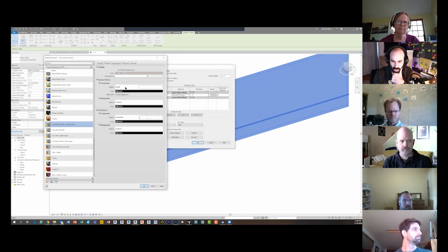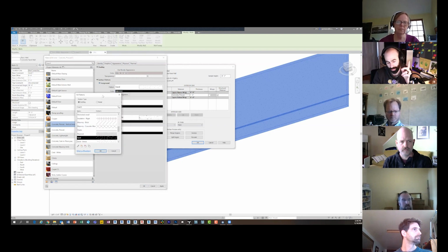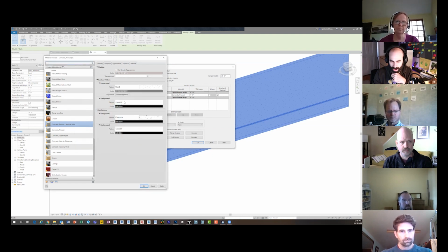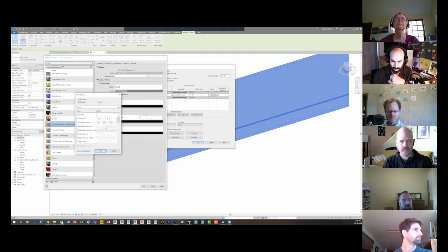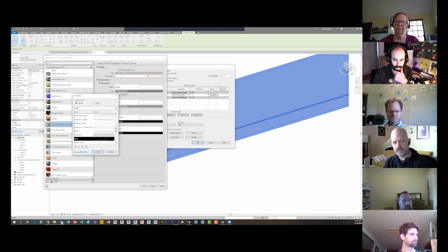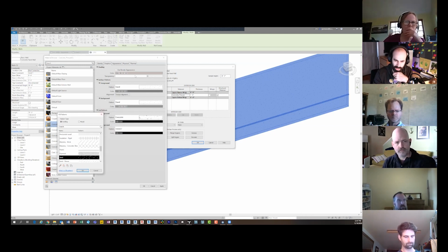And you can see I can just use a surface pattern. Instead of showing it as sand, I can go in here. Actually, pretty neat now with 2020 and 2021. I can leave sand if I want to because it doesn't look bad. I'm going to make it a little gray. And I can add a background, or vice versa. I can use sand as the background, but I can add 2 surface patterns now, which is pretty sweet. So I'm going to add sand maybe to the background because I think that would look better that way. So it still looks concrete, but then I can create. Also, I don't know if you guys noticed this, but you can do 2 model patterns in Revit now.